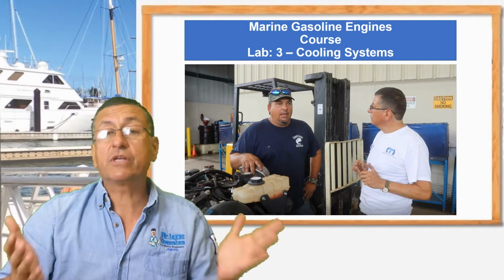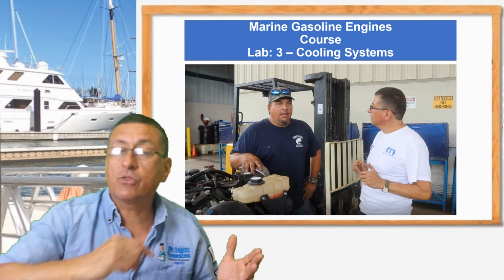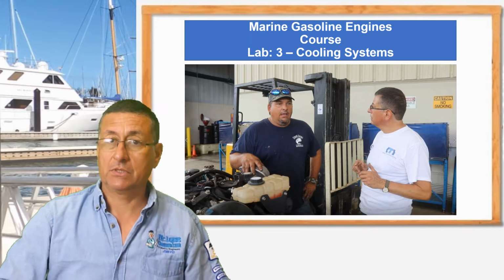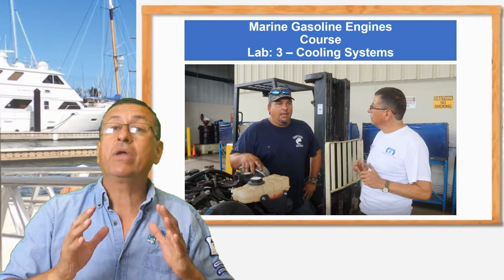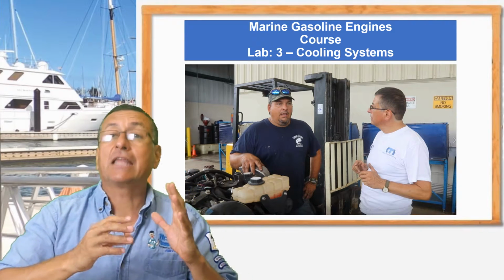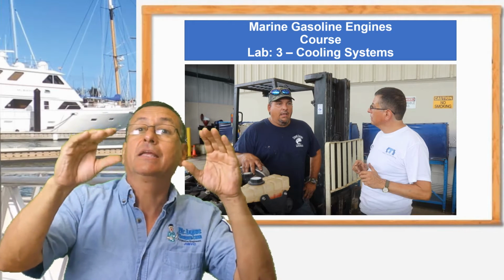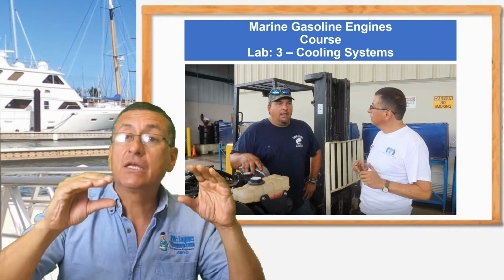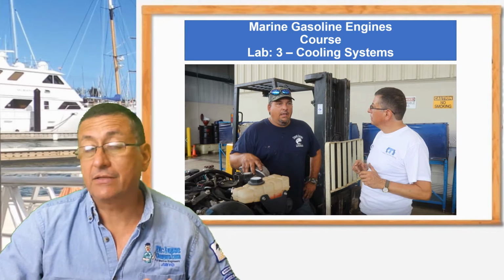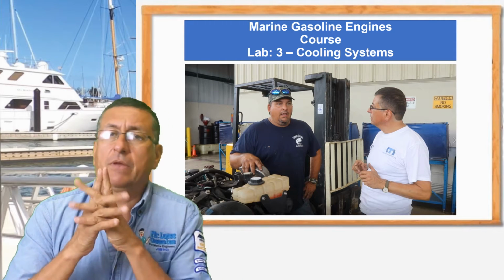We have a raw water system. It's raw water circulating through the block and the head and going out again. And the closed system, or heat exchanger system. In the heat exchanger system, we have coolant circulating through the block and the engine. After that, that coolant enters into the heat exchanger, and the coolant is cooled in the heat exchanger and returned into the block. That's the most common system. We are going to analyze both of them.